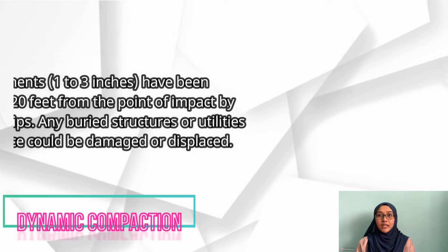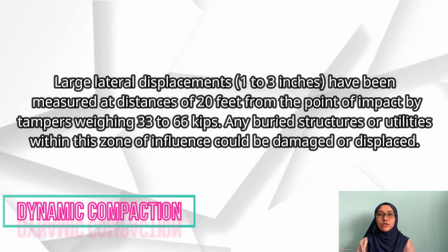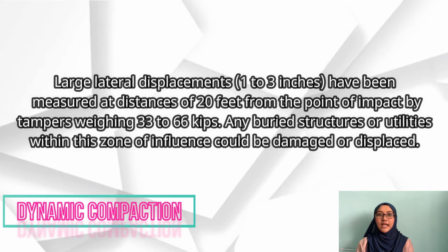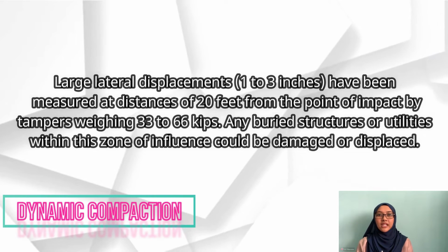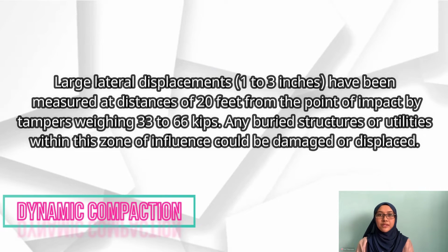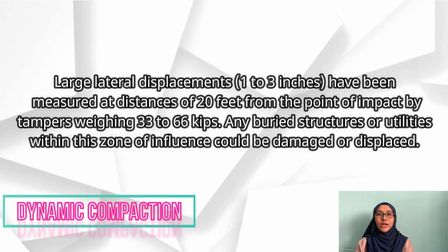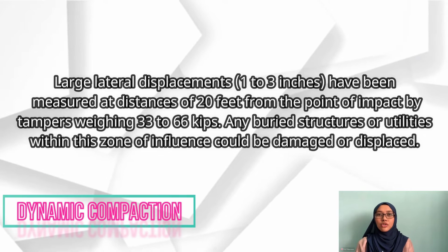For dynamic compaction, large lateral displacement of 1 to 3 inches has been measured at a distance of 20 feet from the point of impact by a tamper ranging from 33 to 66 kips. Any buried services or utilities within this zone of influence could be damaged or displaced.